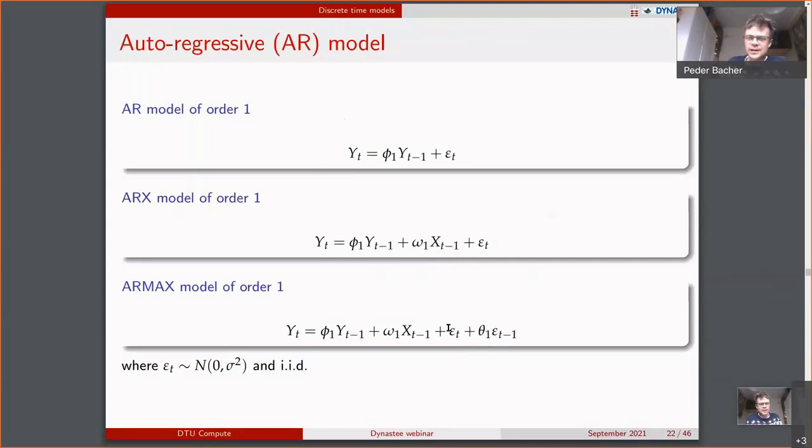If you have a building and you don't measure the ambient temperature correctly, so you have noise on it, then this noise also needs to be filtered by the system in order to have the best model. That's why you have a transfer function on the error. Most of the time we really need that part in the model, but many times we can live with the simpler model because it works well for prediction.